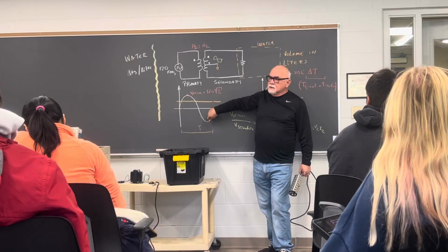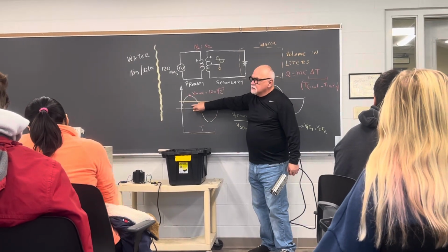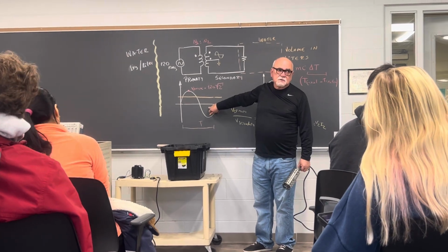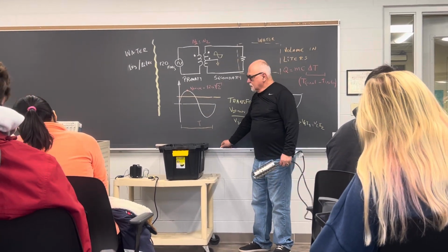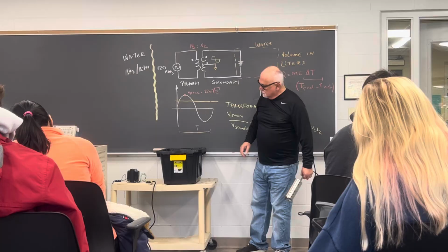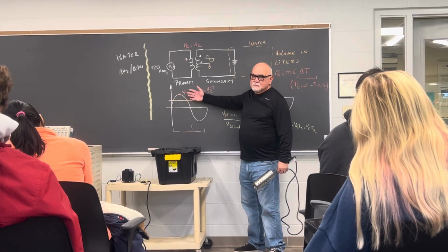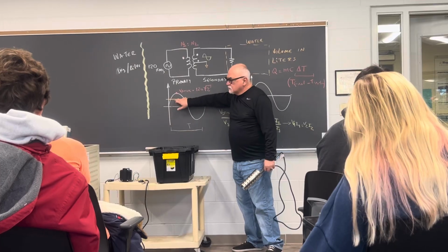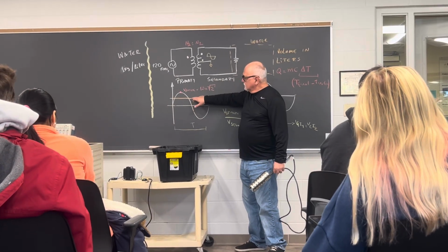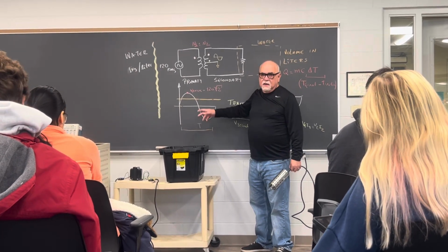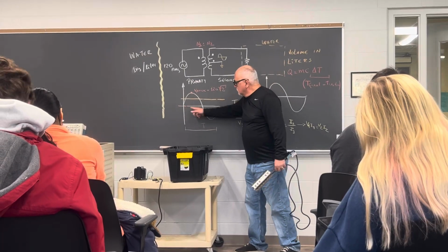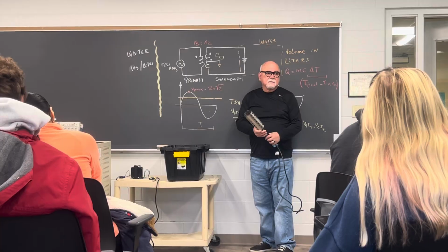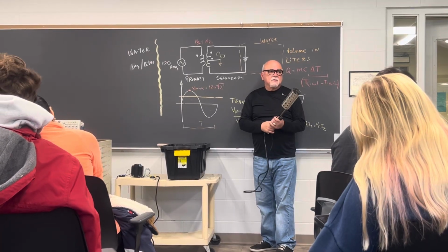And how do we calculate the power? This is positive, this is negative. If I take the average, it will be 0, because the sinusoidal is symmetric. So we square it, and when it's squared, it becomes positive. So you take the voltage squared, and also the DC voltage squared, and you integrate from 0 to T, divide by T, and take the square root of that. That's it. That's the definition of RMS.